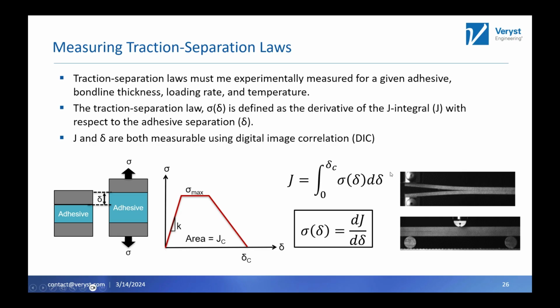So in order to get this traction separation law, what we're actually going to do is measure the J integral as well as separation, take the derivative of J with respect to the separation, and that's going to give us the traction.